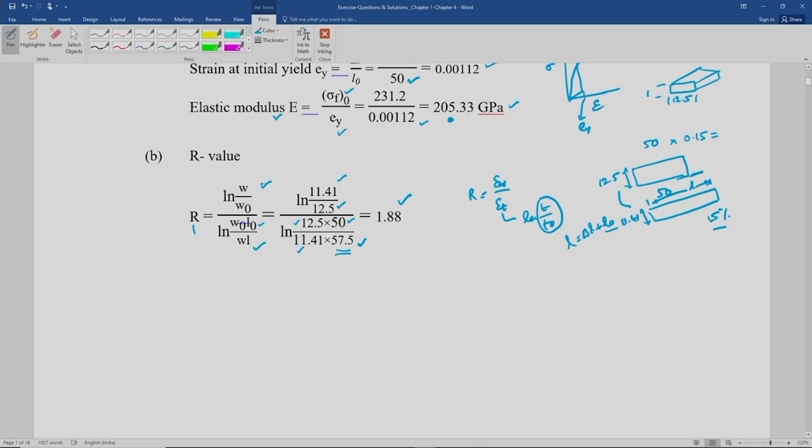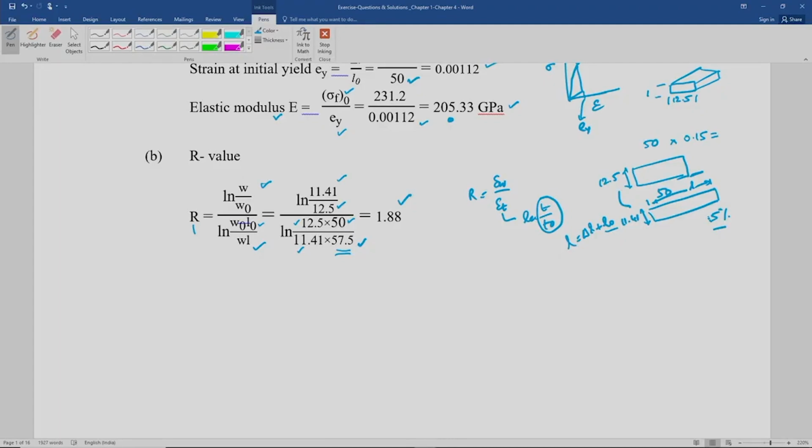And then finally a small part is discussed on how N, yield strength, elongation, R value, M, surface roughness, and homogeneity are important qualities of a sheet that affect the forming behavior. How elastic modulus affects it, that also we have seen. It is better to have larger N and M for better formability generally, and a larger R bar is better because you have large resistance to thinning and you can make deeper components. Delta R should be small to avoid the earring problem. And it is better to have larger M to have large ductility.